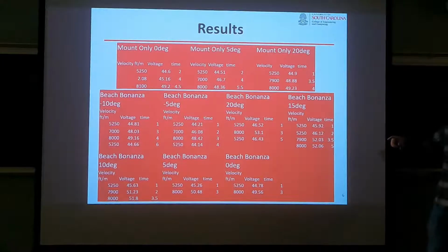And I noticed with some of our calibration data that time completely affects the voltage readout we get off of the sensor, especially when we're doing the hanging weights for the calibration to see how much force is how much voltage difference. That one is very time dependent. I sat there for 2 or 3 hours at the same amount of weight, and the voltage would change relatively drastically over that time without me changing the weights at all. But we didn't notice that issue as much with this. So we stopped waiting as long, as we noticed that after 2 minutes it would sit relatively stable and the voltage would not drop like we had before.